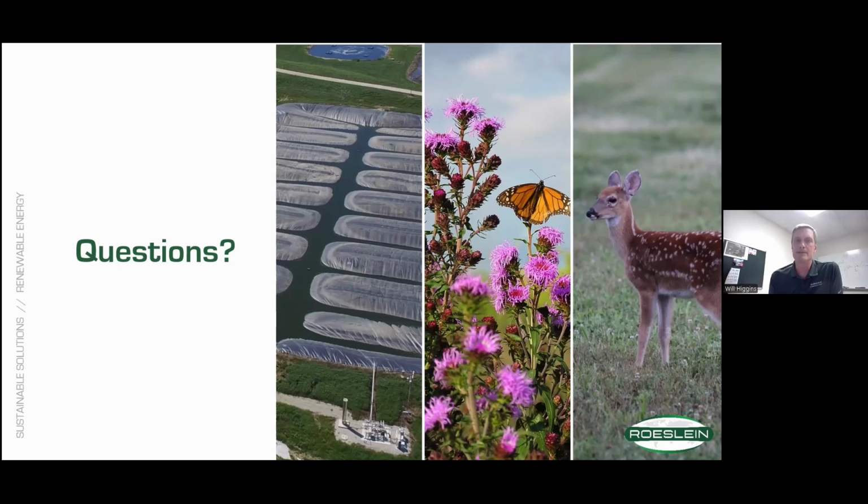And then the amine system, what we've seen so far, at a smaller scale it's just not economical. But at larger scales, like above 1,500 to, I don't know, 5,000 SCFM, the amine systems are much more economical. And that's probably where we'll head as we get into some sites we're looking at, not manure sites, but other feedstocks that might warrant an amine system versus a membrane.